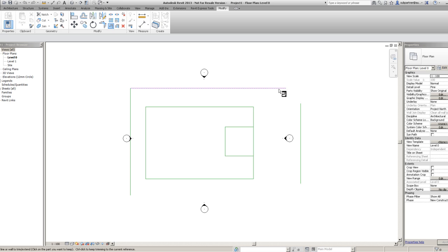You see how it's soft selecting to extend it up? So even though it's missing the line, it will extend it up to the plane that it sits in, like that. And again, pick that one to there. I can pick that one and extend that, pick it and extend it. Obviously I'm having to do it one after the other because it is the single element mode. Again, I'm just going to undo a few of those stages.